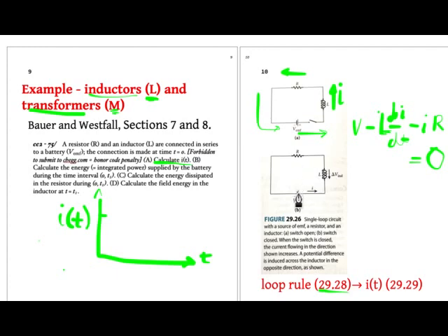So then we'll just have effectively a battery with a resistor. The current will be the voltage divided by R. So let's say the current starts down here. Well, actually, if I start out with no current, then the initial current will be 0, and it'll come up and level off at the value V over R. It'll approach this point exponentially. Well, okay, I'm not going to work out the solution here, but it's in the book.